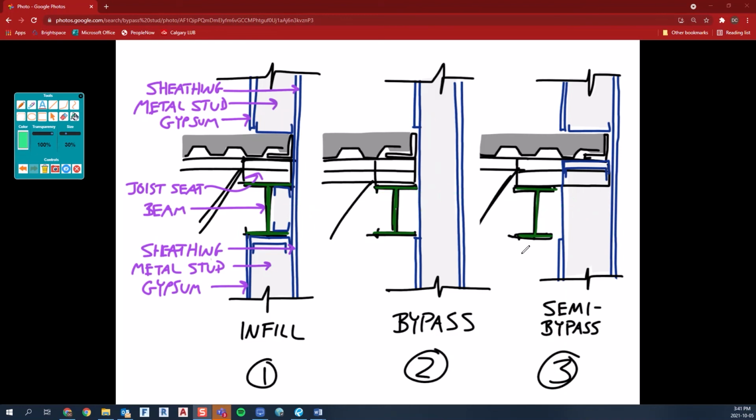and you still get the other benefits of the bypass system by getting more floor space and not having to worry too much about that coordination of fitting the beam in the stud space, and the column and the stud space, and all those benefits basically of the bypass system. But you just got rid of, maybe, I mean, I'm not a contractor, but maybe some trade sequencing, and then of course the fire stop situation.